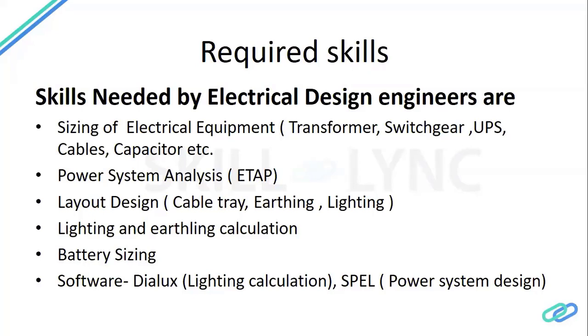The software generally used apart from the ETAP are Dialux. Dialux is very commonly used software for the lighting calculation. SPEL is a power system design software, where you can prepare the load list, you can decide the cable, you can prepare the cable schedule. Revit is also one of the software which is generally used in the building sector. So these are the major skills required by the electrical design engineer.